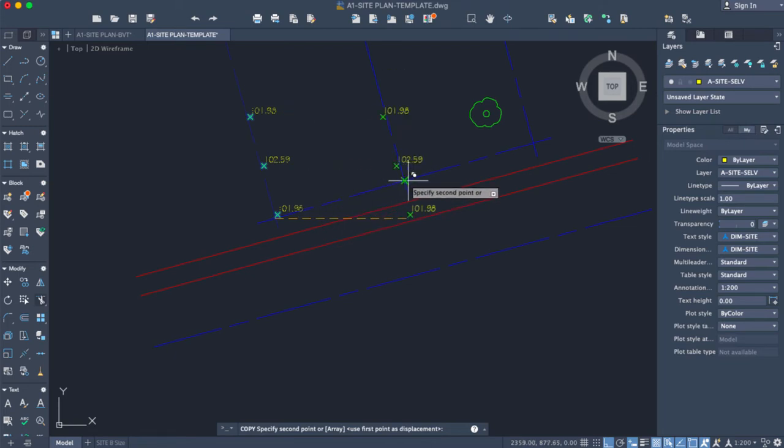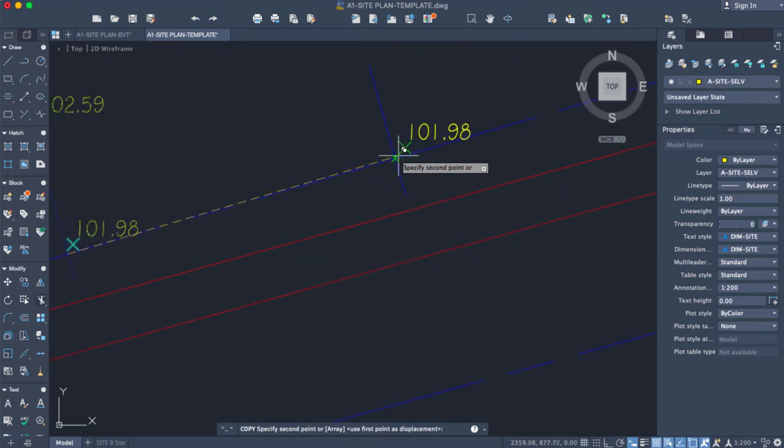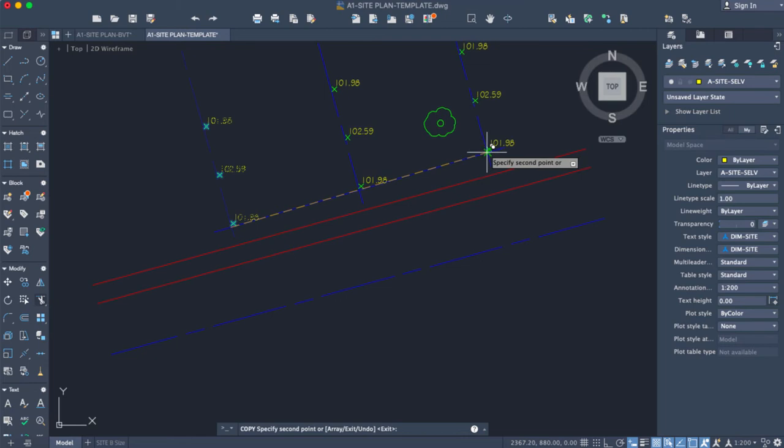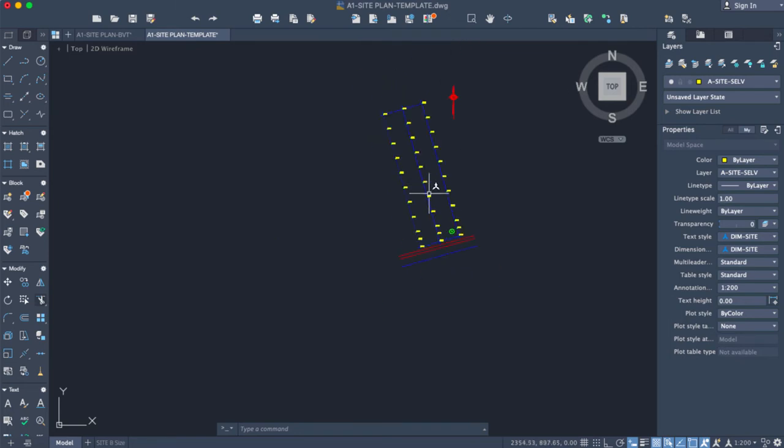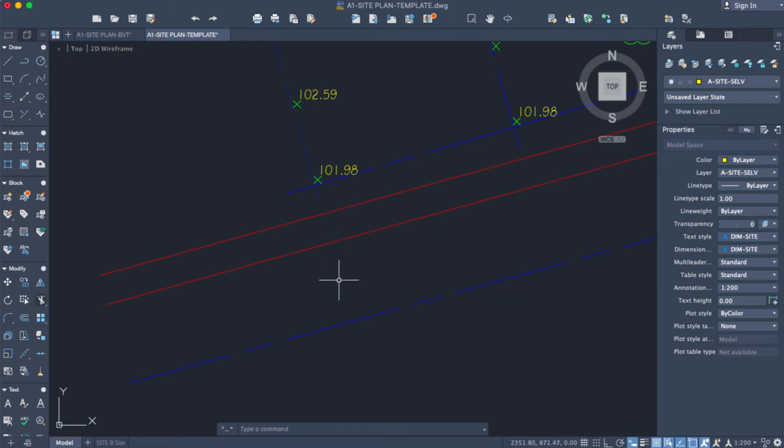So I'm using that as a base point. Make sure you do turn off your ortho, and then use the next reference line. So you just place it by left clicking in there. So once you do that, again, if you look at the other side of that property line, the side close to the sidewalk, there's again the elevation grading for that, it's showing as well.